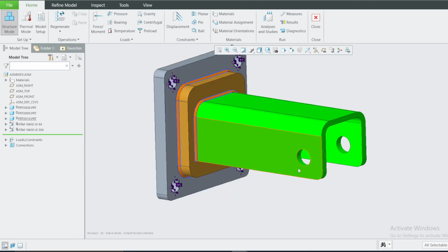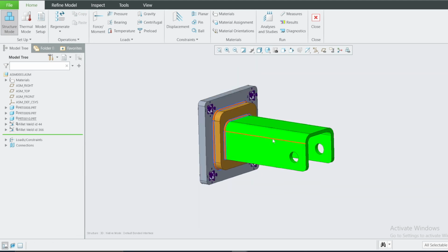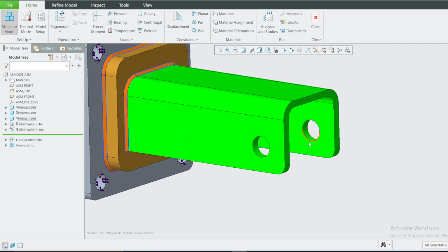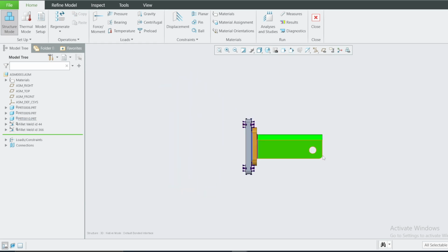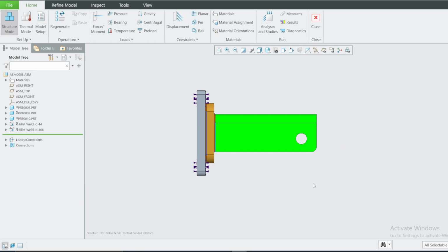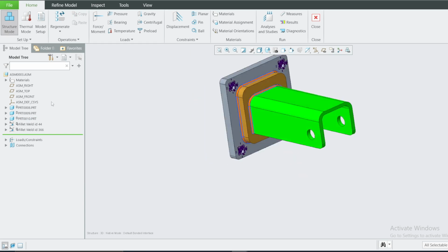Then I need now to define my load. Something to note is my load will be hung onto this. We are going to have a rope that is connecting these two holes. If my load is somewhere here, I'm going to create a point to represent my load case. Basically, my load is somewhere here. Therefore, on the front plane, I'm going to create a point.